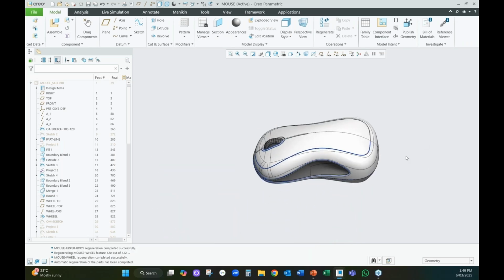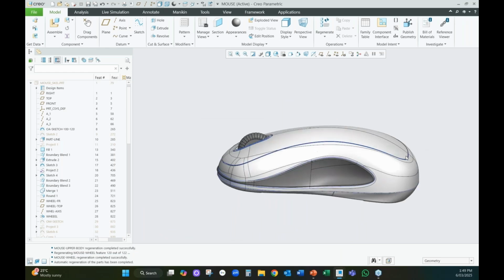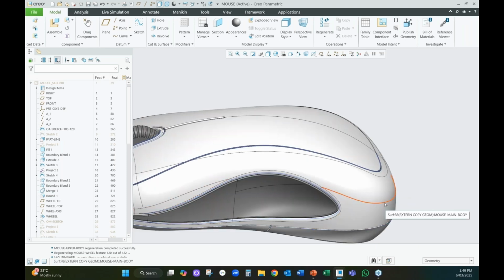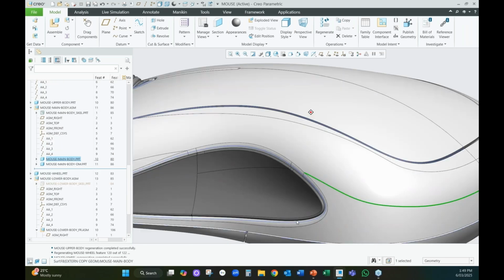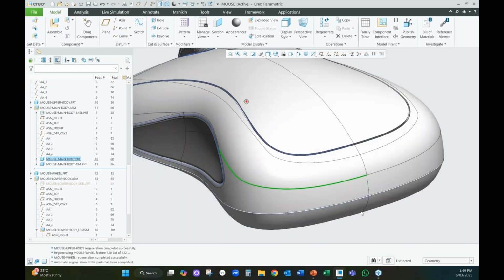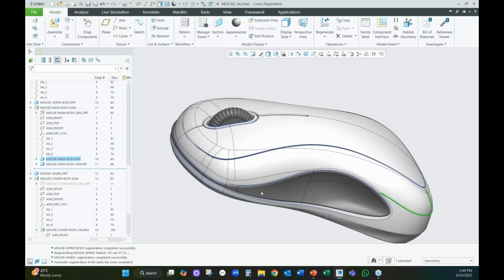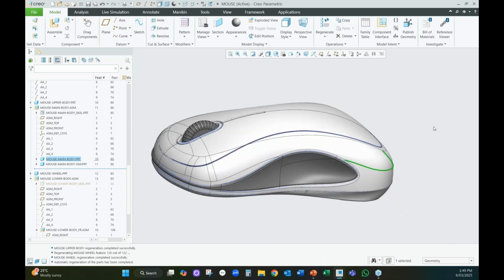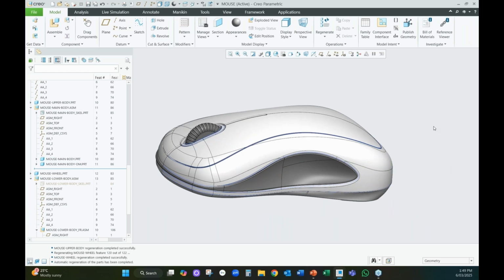You will have features like drafts and rounds, which almost would guarantee to fall over to some extent because they're very constrained by these intersection lines and your tangent lines, which is why I always leave them showing, to give you a good understanding of where the interactions between those are going to happen.